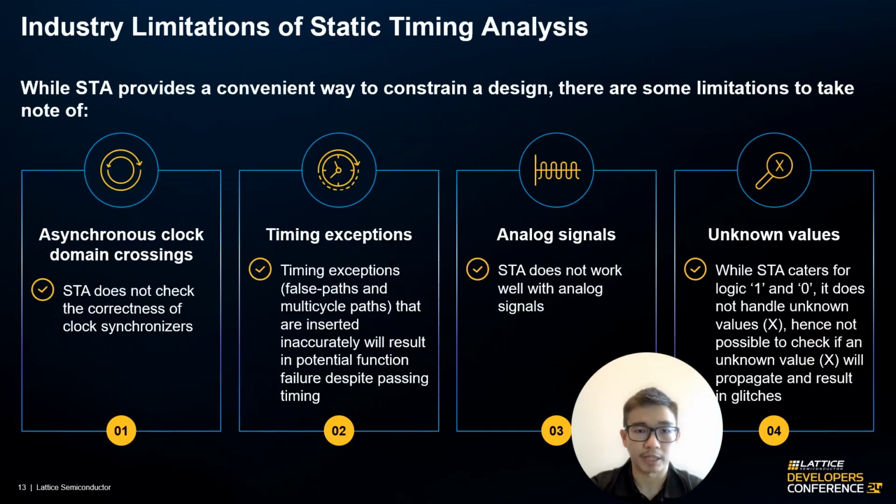So far, we have discussed the importance of static timing analysis, but it is not without its limitations. First and foremost, STA does not check for clock domain crossing, also known as CDC, paths. It is the responsibility of the logic designer to ensure that these transfers are being taken care of in order to ensure any potential metastability issue is minimized. The same applies to timing exceptions. While applying constraints like false path and multicycle could help resolve timing violations, it must be ensured that the circuit has been designed in such a way that these constraints could be applied.